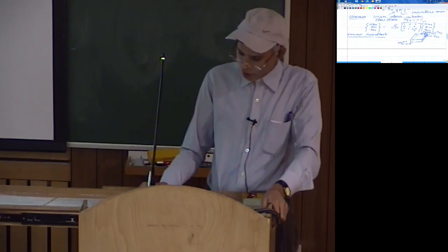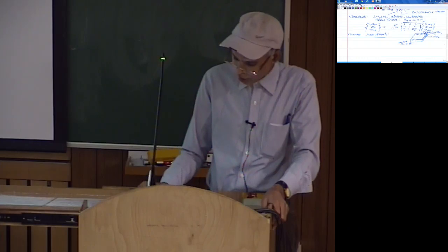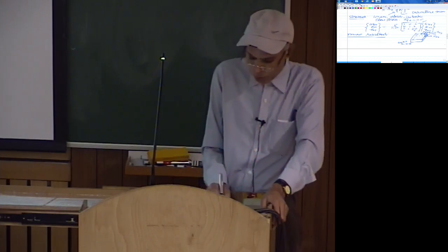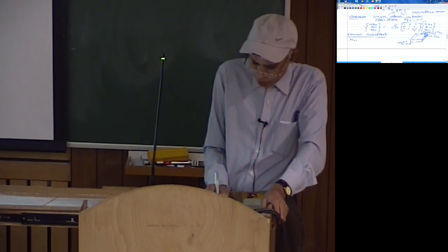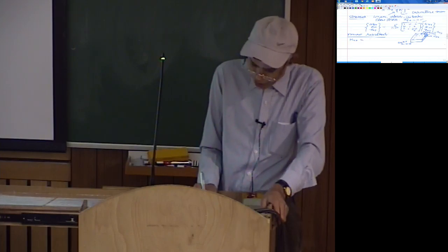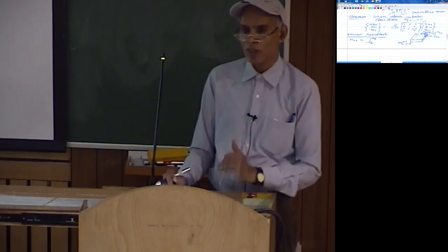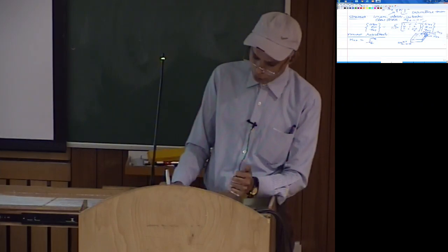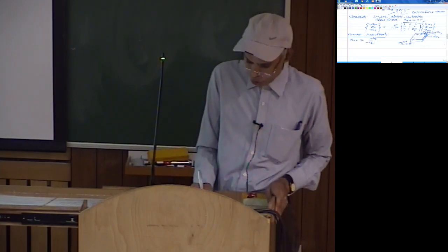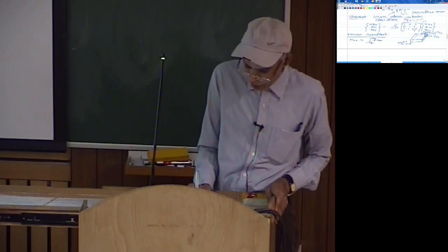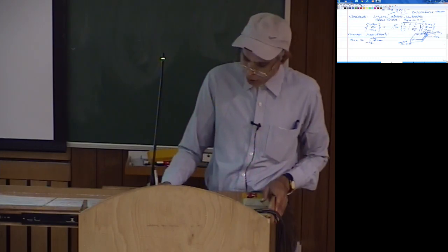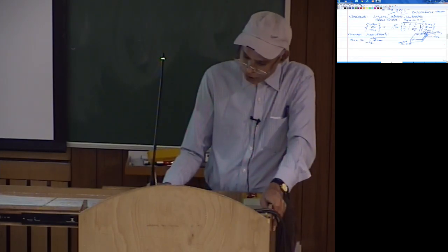Now we multiply this stress sigma xx with the distance z and integrate it from bottom to top. We define that as the moment resultant mxx. So mxx is defined as the integration from minus h by 2 to plus h by 2, where I am taking the z equal to 0 surface as the mid surface. The z coordinate varies from minus h by 2 at the bottom to plus h by 2 at the top. So you will have z into sigma xx dz. I am only taking the distance along the z direction, not the total area, so it will obviously be the moment per unit y length.